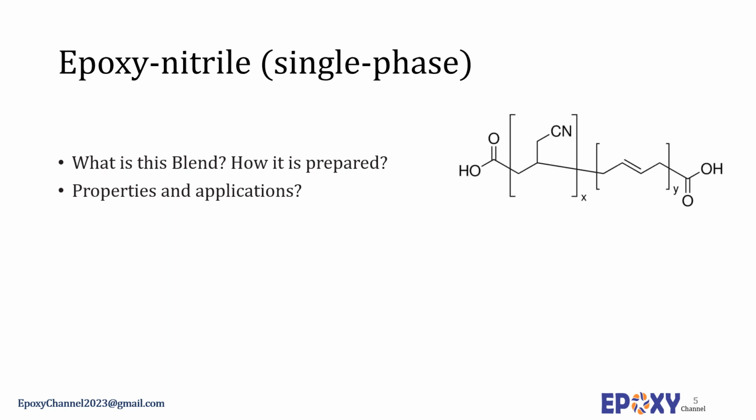The film is widely used in aircraft structures where a high degree of peel strength and good resistance to moisture is required. For adhesive application, the main focus is usually on improving shear and peel strength. If this blend is incorporated in epoxy systems, a significant improvement in toughness and elasticity in the cured bond line results, which means a high tensile shear and peel strength.